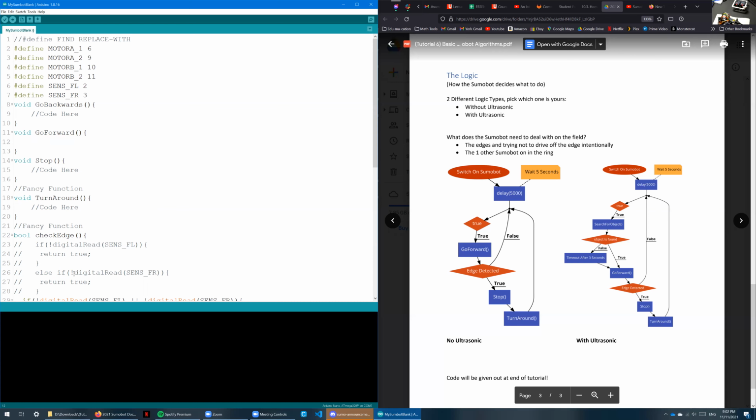We need 4 commands. Analog write, because we're controlling 2 motors, and each motor has 2 inputs to the motor controller coming from the Arduino, and that'll turn out basically, feedback to control 2 motors. So analog write, if I can spell analog correctly. Thanks, syntax highlighting, really saves me there. And then we analog write, and I'm going to write 255, which is the highest value you can write to a pin. And we're just going to do motor A1.